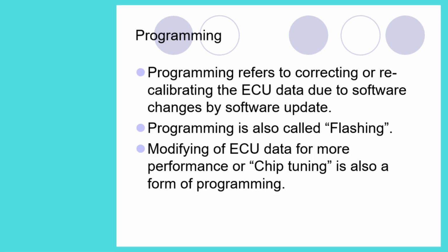Programming refers to the correcting or recalibrating of the ECU data due to software changes by software update. Programming is also called flashing. Modifying of the ECU data for more performance or chip tuning is also a form of programming.